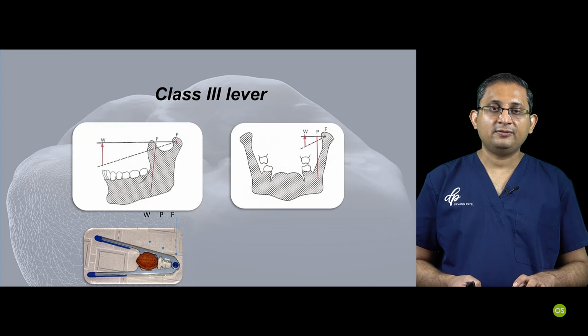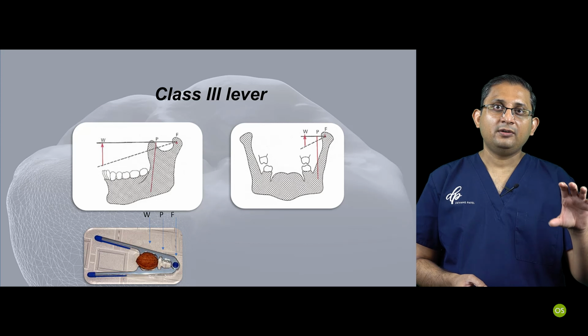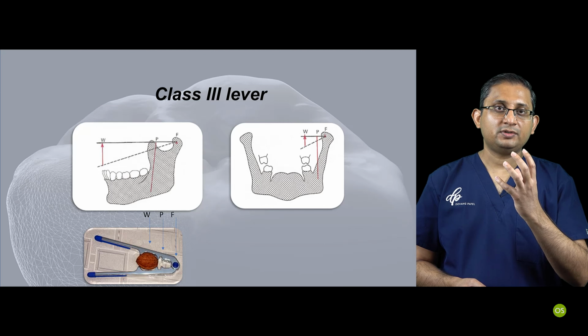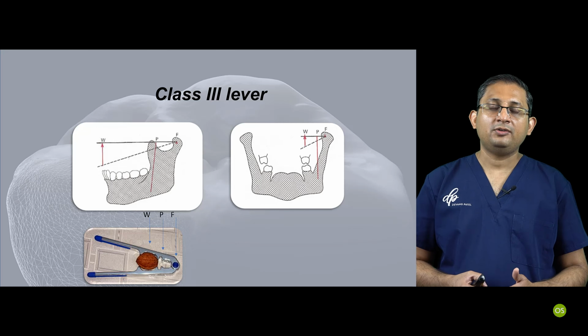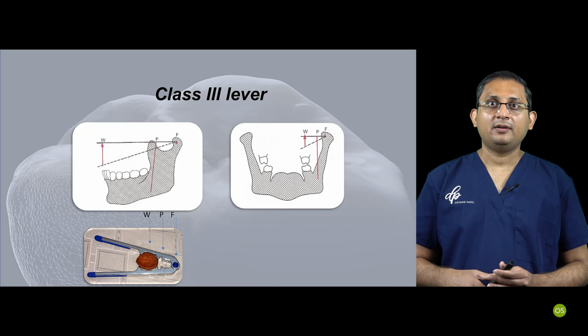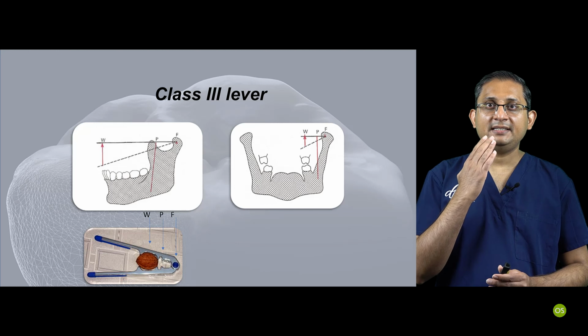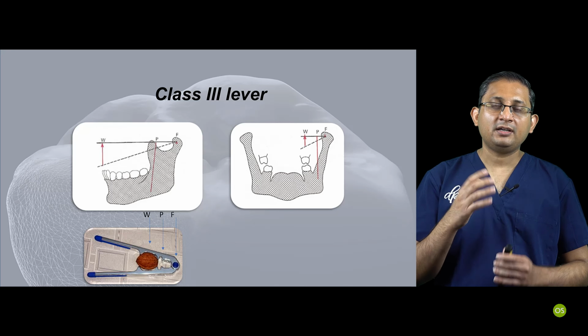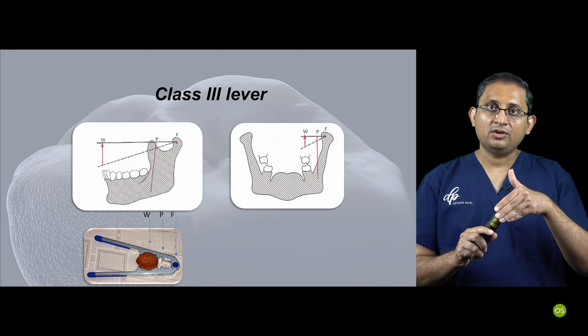And that's the essence of it, that you want to keep the work away from the force as much as possible. And when we say work, we mean guidance. When you are guiding the teeth, teeth are in contact. So when I say work, it means teeth contact and guiding contact.